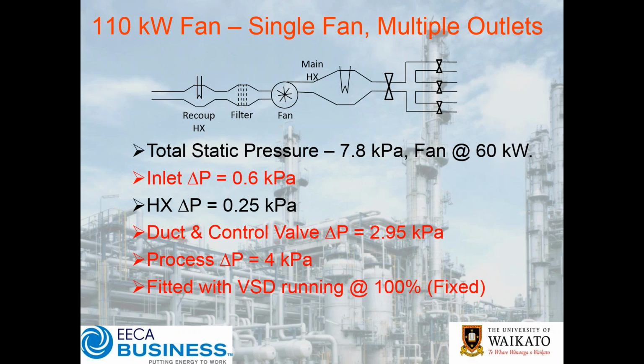And then we had a secondary damper valve on the 3 parallel outlets, and then of course the fan was also fitted with the VSD. Now in this particular instance, funnily enough, the VSD was left running at 100%, so actually the VSD was introducing a number of additional modes of failure to the system from a maintenance and reliability point of view, adding a whole heap of capital cost and costing about an extra 3% in energy without providing any real value. So really not an ideal situation.